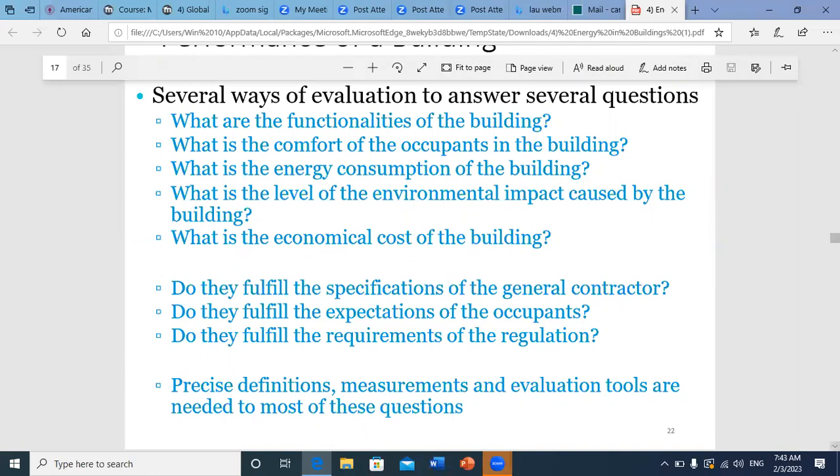You don't care a lot during nighttime what will happen. So you can put the orientation in a way to ensure, whenever you have sun hours, a good sun penetration between these times. You can choose the orientation in a way to reduce heat flux during summer, etc.